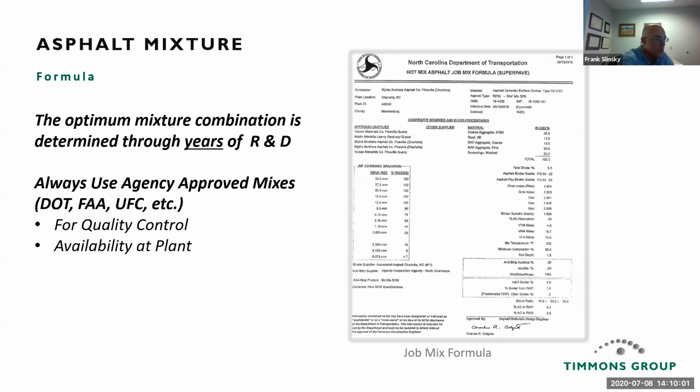Over to the right, we show a typical job mix formula for NCDOT pavement. That's what the formula is based on, and we'll receive this job mix formula as a submittal and review it against the DOT spec.